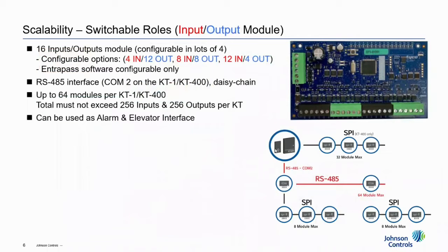So we also have an input output module, which has a switchable role. Okay, what I mentioned about switchable role is that this input output module, right? Okay, it has 6 interfaces. And these 6 interfaces, you can configure it at will. Okay, whenever you want, you can change the setting to switch it from an input and output. Okay, vice versa. You just can toggle the modes. And most of the time, we have found that whenever we have inputs and outputs that we install on the site,